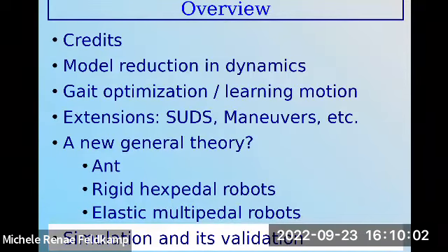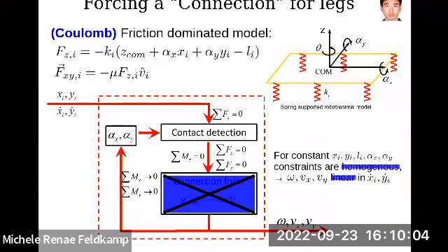So my student Dan tried to write a simple model where you imagine the robot has a bunch of spring legs that have friction on the ground. There's a little problem with that model, which is that to get a connection type model, to get this linear relationship between input velocity and output velocity, you need homogeneous constraints. You need the mathematical structure that just isn't there because Coulomb friction doesn't behave that way. The kind of friction that you have dry on dry contact that you learned in high school physics just doesn't have the right behavior for this.